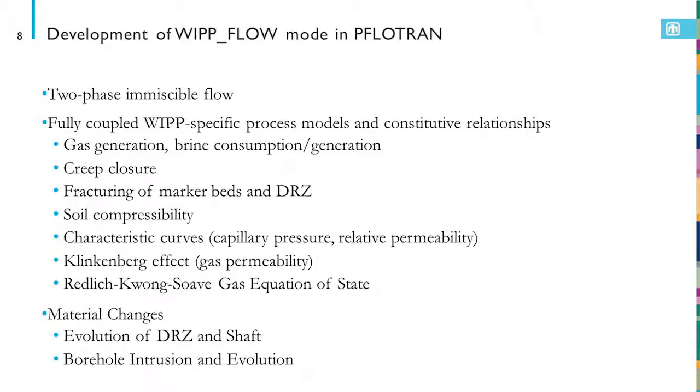Development of WIPP flow mode in PFLOTRAN involved implementing two-phase immiscible flow without an energy equation in there. Coupled into that two-phase immiscible flow, fully coupled into that, are several WIPP-specific process models. And those include a gas generation term and a brine term that could be either consumption or generation due to things like corrosion of the waste packages and biodegradation of any organics in the repository.